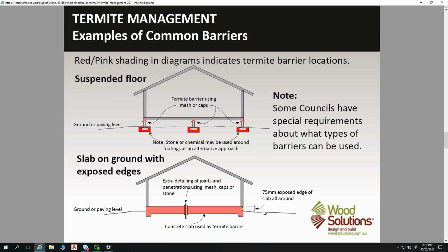If you carry your paving up to the height of your slab or beyond the height of your damp course, that is bad for several reasons. One is that you end up sending moisture into your house if you've got any slope towards that, but then also it's a place for termites to just go very easily into your house, to eat the house as well.